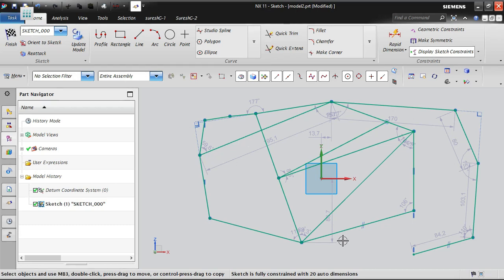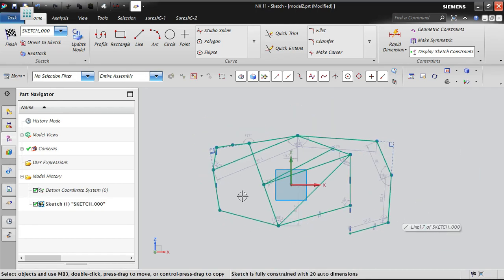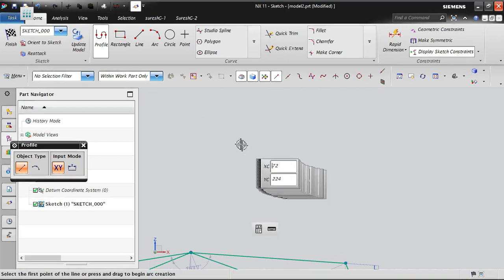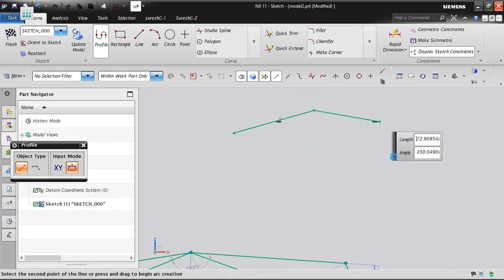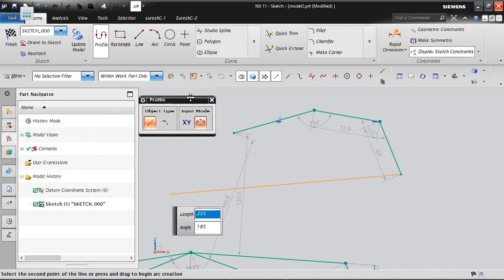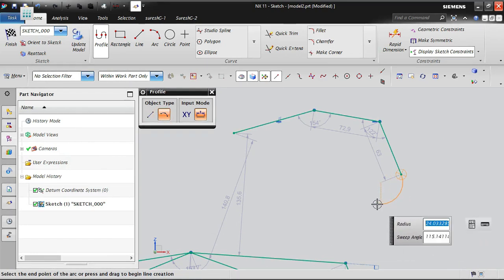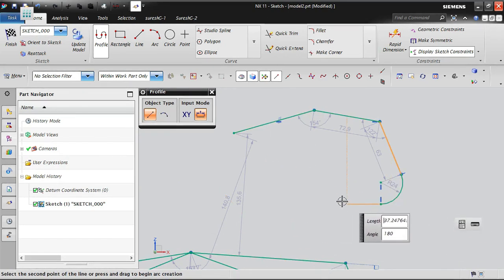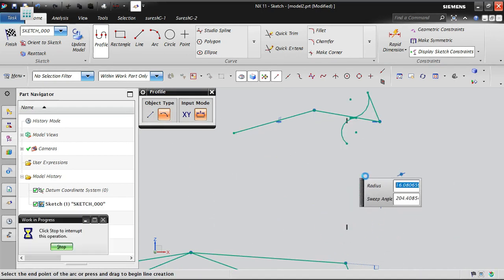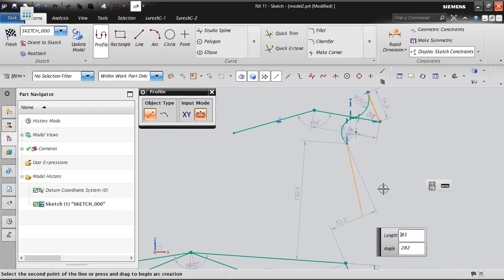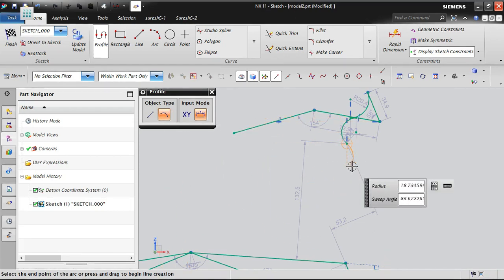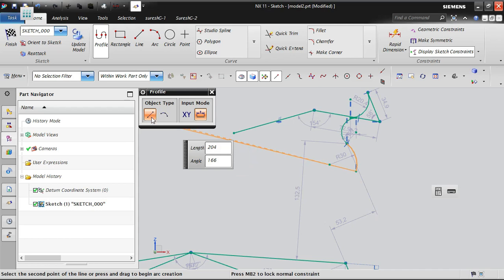Alright, so this is about profile of a line. In the same profile of a line, we can create even the arc also. When you are about to create lines, for example, now I am creating a line, and a few more lines I will create. I wanted to continue with the arc, so you can click on this arc button. You can see here, click on this arc button and you can create the arc like this. Again it will continue with the line. Again if you want to go for the arc, it will continue with the arc. Again if you want to go for a line, you can go for the line option. Suppose you wanted to continue with the same arc, you can press the arc button one more time so that the arc will continue. Now I wanted to continue with the line, so you can go for the line option.